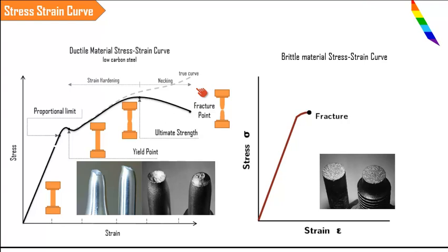That is one of the most ductile materials that is available. So these materials can be drawn into very thin wires. That means the ductility is high. Such kind of materials will be categorized under the ductile material. And brittle materials are the ones which will not undergo high deformations. So the failure will be all of a sudden. So we cannot expect to have a larger elongation.